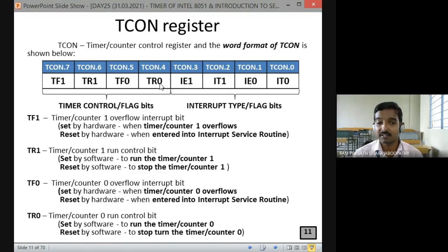See, if you know this, you can program the timer easily. Fine. We have written delay programs, correct? In the lab we showed you how to write delay programs, correct? That delay program is approximate only. It is not an exact delay time. For generating an accurate time delay, you have to use the hardware timer. So for an LED blinking program, once we learn timer programming well, what can we do? For time generation, what can we do? I can program the timer or counter. Yes, is it clear?